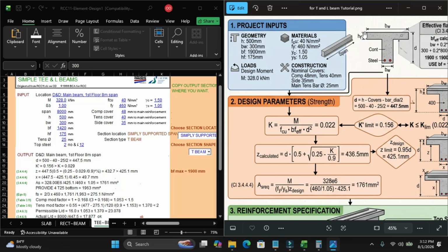It correctly gets this one as HF. This is the thickness of the slab, but it is part of the overall height of the beam, because these beams are usually designed to support a slab. So this part, HF, is the thickness of the slab part of the beam. So you can see it here. Okay, it tells us what the span is. So if you don't have any idea of what the span looks like, you can see it. That's the length of the beam, the span.